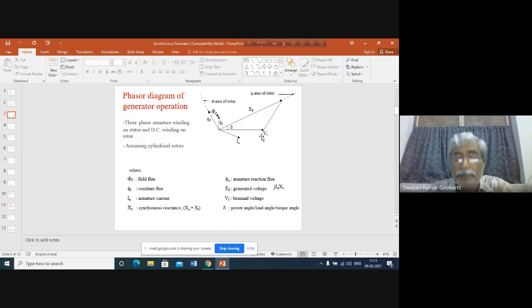Okay, you cannot change it, because the power system is maintaining that frequency constant, and your generator is really very small compared to the capacity of the total power system. That's why, whatever may be the power variation of your generator, it has no capability to control the frequency of the infinite bus, because the infinite bus is of infinite capacity. This is our assumption. In practice, that will not happen, but those things we shall be discussing later on.